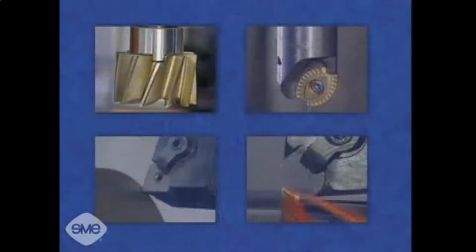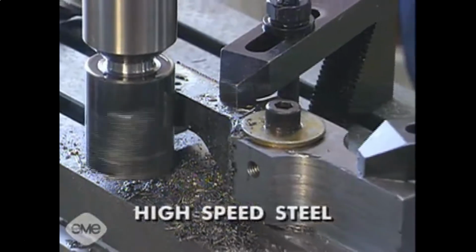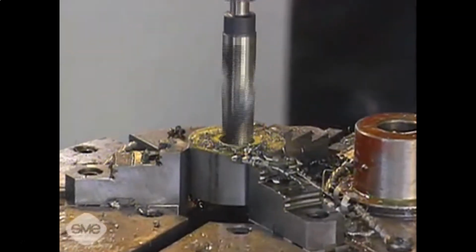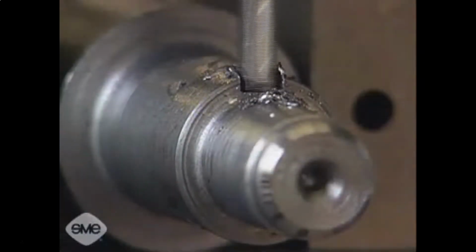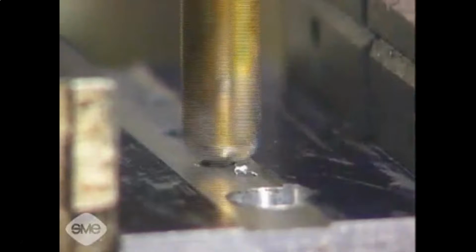There is no ideal cutting tool material, but the rapid evolution of tool materials has given us a wide choice to meet any need. High-speed steel tools are commonly used in tool rooms and in low-speed operations. Round tools such as drills, taps, and end mills are commonly made of high-speed steel. Coatings have extended the applications and cutting life of high-speed steel tools.